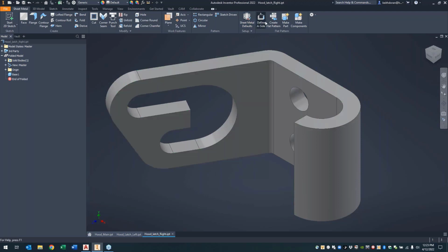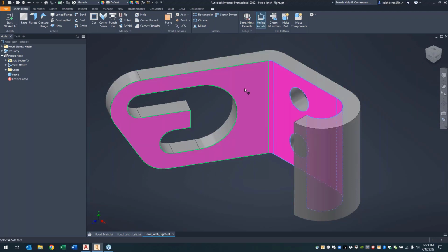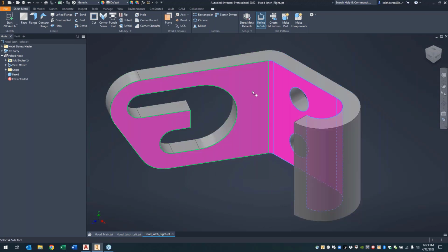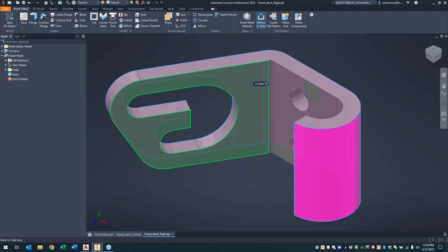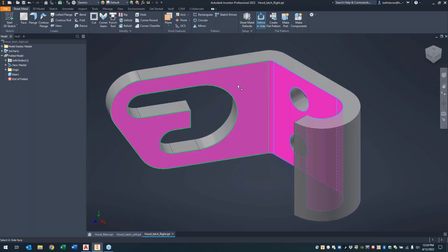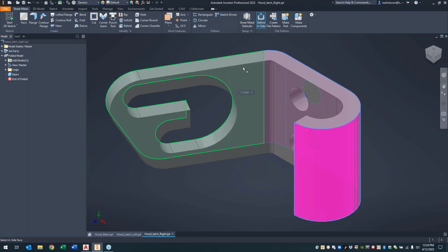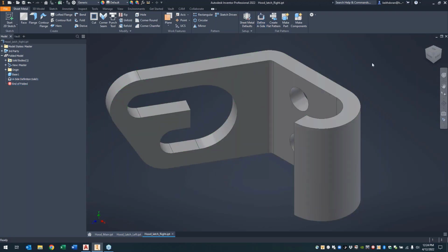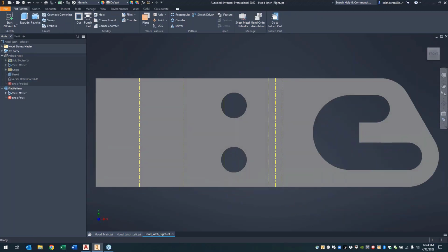Now that I've done that, when I go to the define A side, this is another really good indicator that something is working properly. When I did the define A side on my Inventor part that somebody modeled for me, I saw that this didn't trickle around. It didn't automatically wrap, and that pretty much told me that there was something wrong with it. But in this case, the A-side calculation is figuring out, okay, this is all continuous thickness throughout, so we're going to utilize that for our bend definition. And from here, I can now thicken this component.